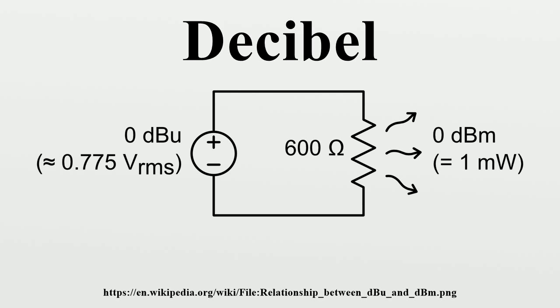For example, a system consists of 3 amplifiers in series, with gains of 10 decibels, 8 decibels, and 7 decibels respectively, for a total gain of 25 decibels. Broken into combinations of 10, 3, and 1 decibel, this is 25 decibels equals 10 decibels plus 10 decibels plus 3 decibels plus 1 decibel plus 1 decibel, with an input of 1 watt.